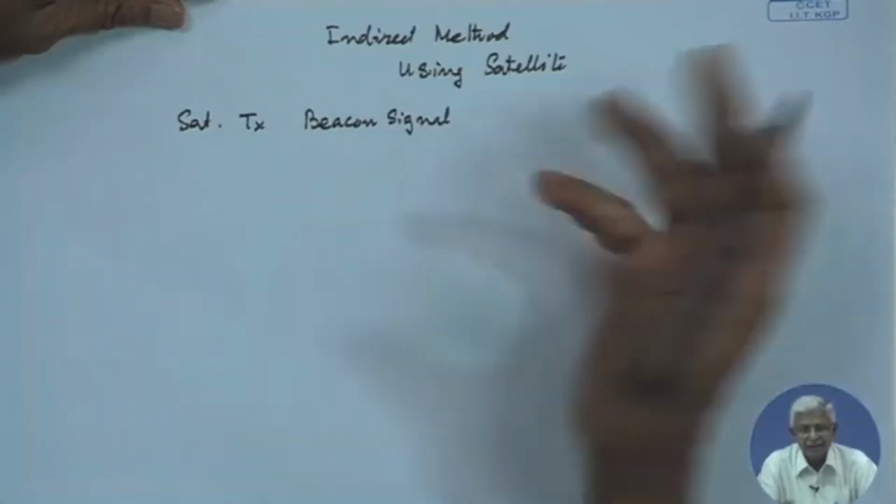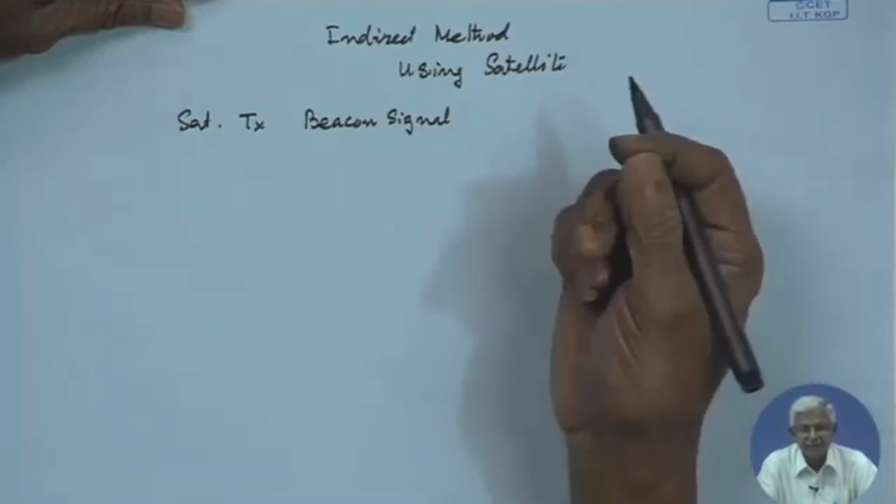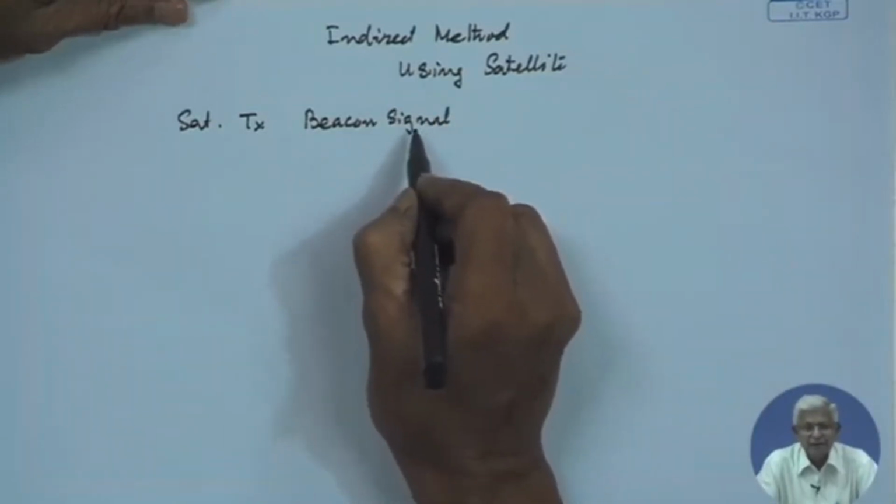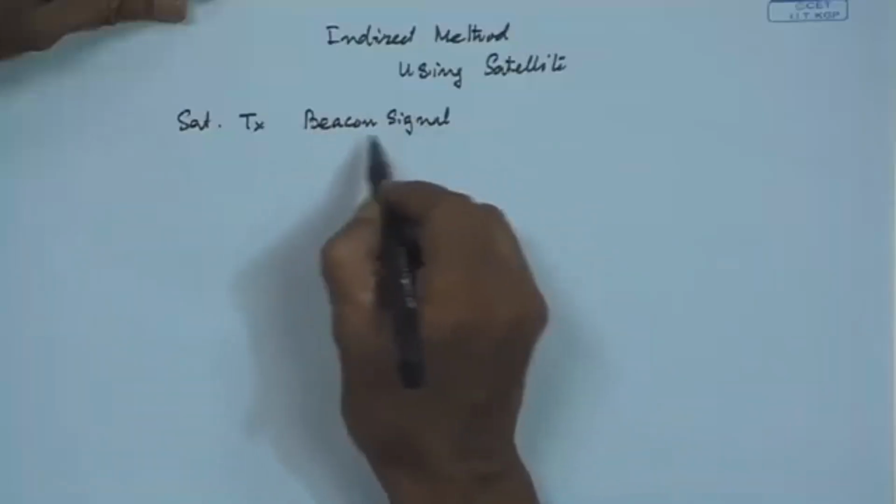Where is the satellite? It is for a large antenna to point to the satellite. There is a constant EIRP at a particular frequency without any modulation, and it gets transmitted. It is called beacon transmission. So, for that beacon signal transmission, the beacon EIRP is very well known and well calibrated. It does not change, otherwise the pointing error will be there. So, you can use this beacon signal reception as a G by T measurement.